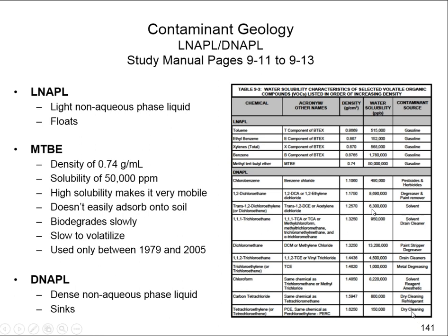So look at some of these, dry cleaning plants are also ones that they might ask about, where we have PCE. TCE is also important, where we have vapor intrusion, as well as the DNAPL. Anyway, looking at that can give you an idea of where to expect things. We don't need to worry about the water solubility values, but just knowing that they're lighter or denser than water.